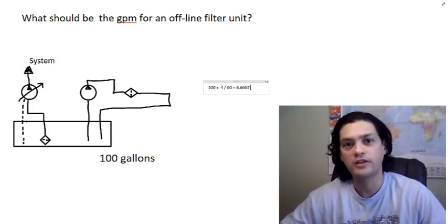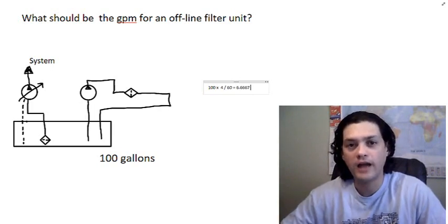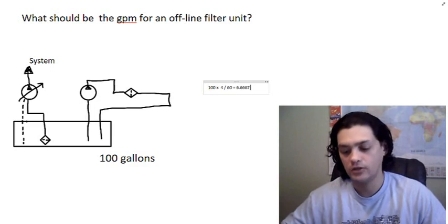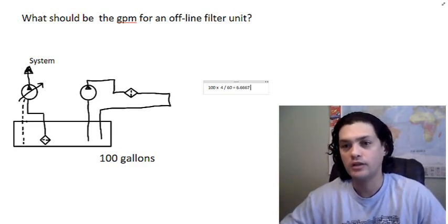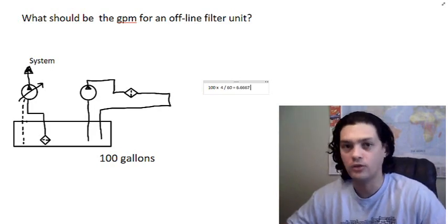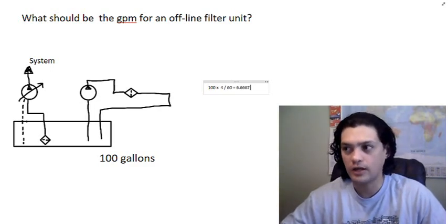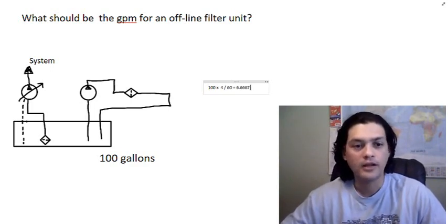Let's say different manufacturers of piston pumps likely all have the same number for the contamination levels you should use in your piston pumps, in your vane pumps, in your proportional valves. Even though they're different manufacturers, most of them have the same contamination level that you should follow. You can look it up in the manufacturer's records, and there are also standards out there. I should put some apps later, but that's basically the idea.